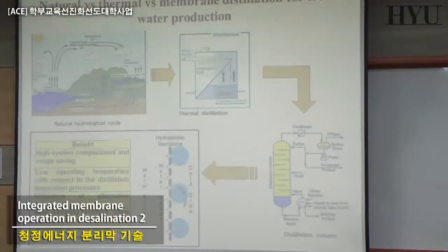Membrane distillation is using exactly the same amount of energy you are using here. It's a thermal system, and in principle exactly the same, in the same boundary condition. So the benefits in energy can be overall, because you just have a smaller size, and you can operate at low temperature, not high temperature. In this case, it's better. But the amount of energy necessary to evaporate 1 cubic meter of water in here is exactly the same as here. And if you tell me that it is different, you are making mistakes. Don't make mistakes.